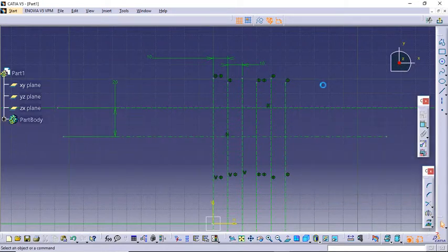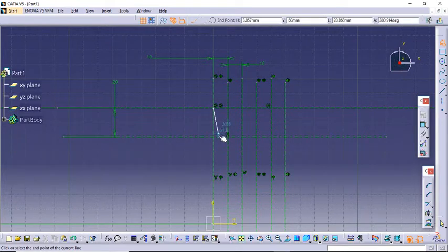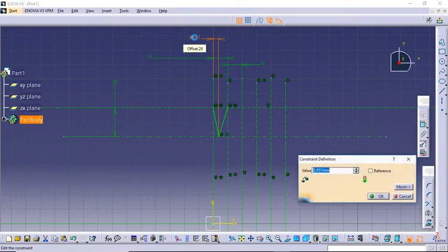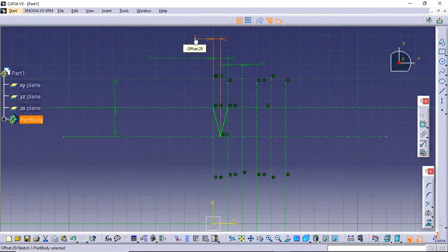Okay, looks good. Now let's start drawing the groove section. These are V grooves, so it will simply look like this. Let me make it symmetric. Symmetric means I will have the same distance from both of the 10 mm line. So 5 mm looks good.